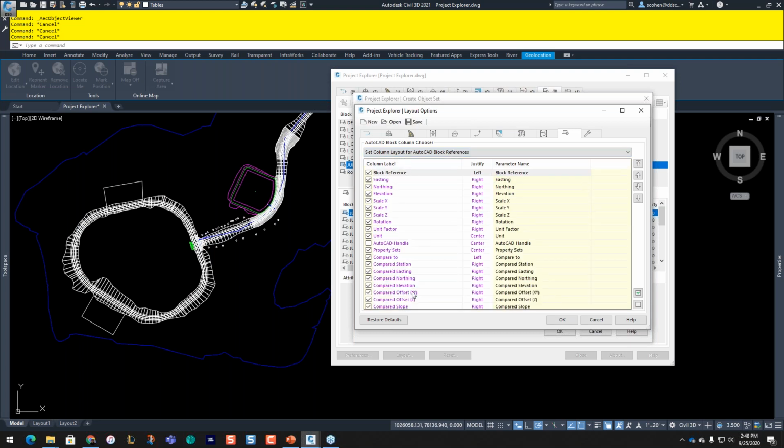All right. So again, notice how it lists a whole mess of properties. I don't want that, so I toggle all these off. I want the tree type. I'll change that in a second. I want northing, and I want easting. We'll get elevation later, because I want to show you how you can change this afterwards, and all is good. Now, I want the order to be northing, easting, not easting, northing. That's how things are done.